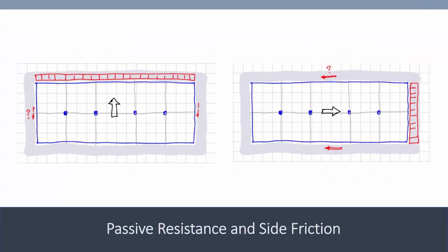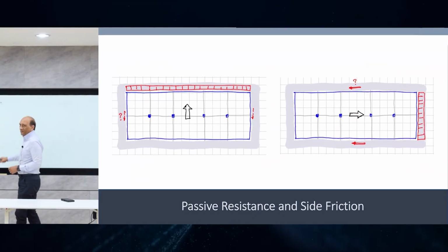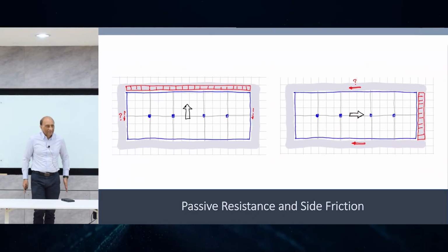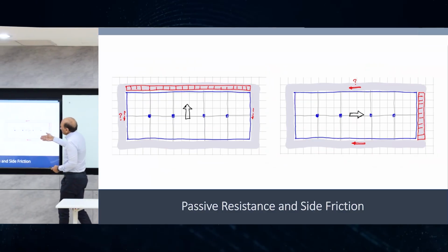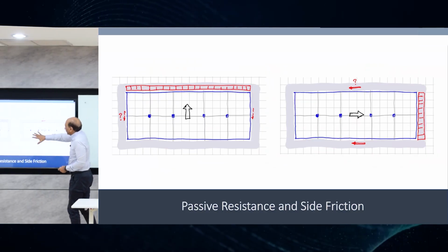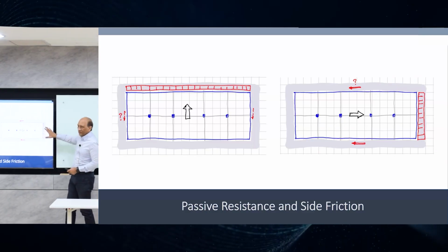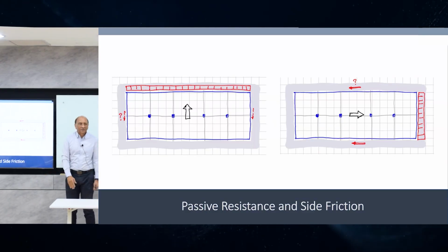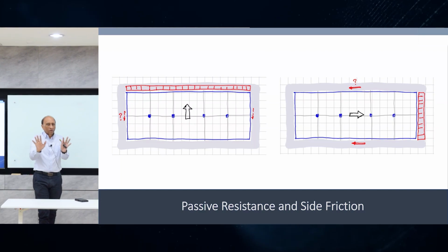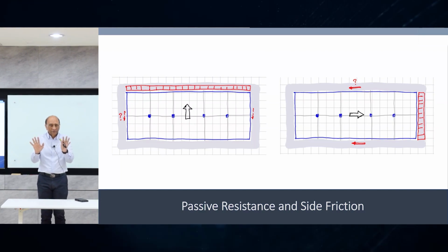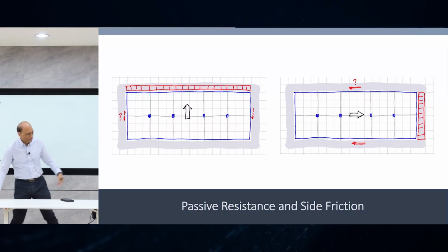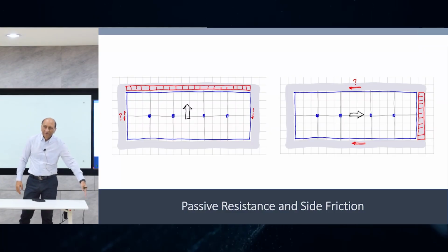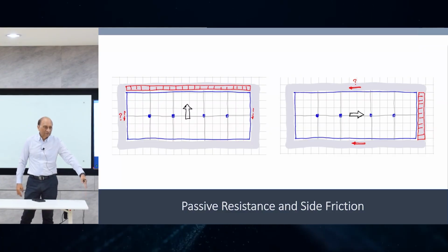Look at the plan. Typically buildings are very long, the front is small, and buildings are deep, right? So when the earthquake force is coming in this direction, the whole building is trying to move this way, and only this short wall is resisting all of the force, right? Total mass multiplied by whatever factor, you have a lot of force coming to the building. It's moving like this table is moving in this direction. So only this wall will get all of the passive pressure.